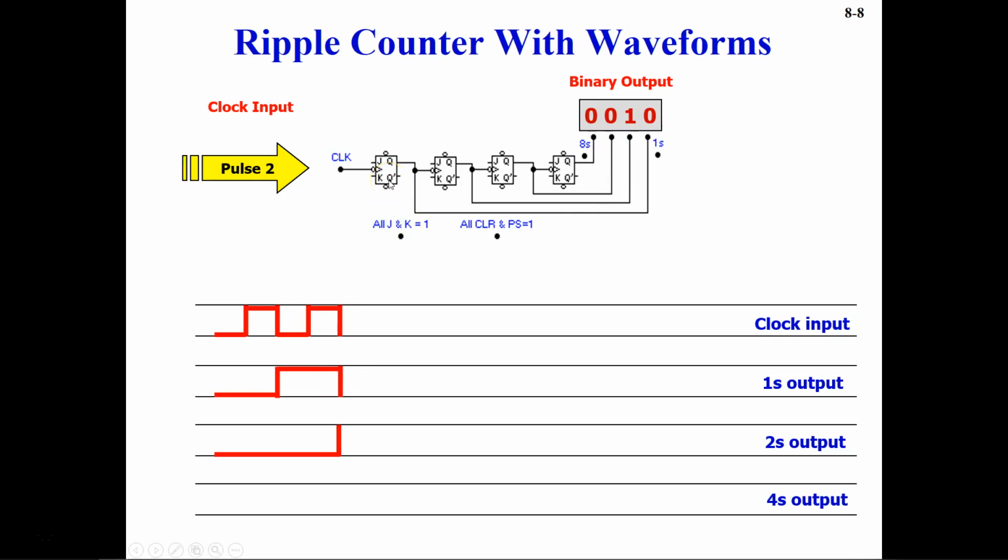But at that second pulse, you have 1 going in there, and that's why in the second pulse this will basically toggle. In the first pulse this was not toggling because the clock was just going into the first flip-flop, and corresponding to that you were getting the toggle condition, and the rest were receiving nothing at that particular instance, so these were not turned on, they were all off.